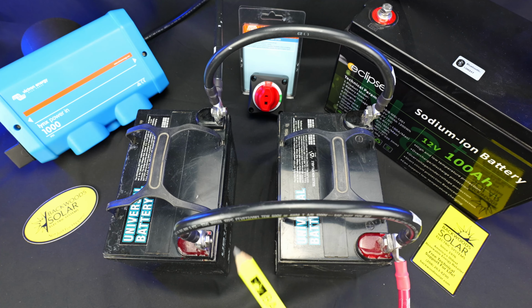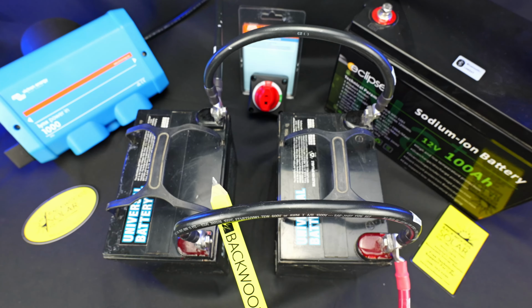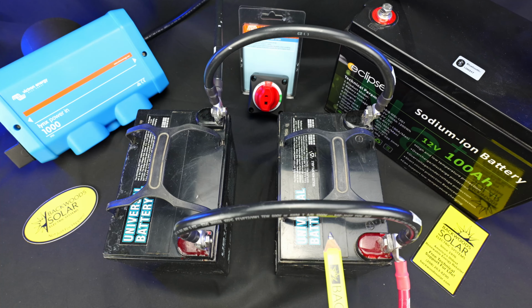In our example here with these two 12 volt 35 amp hour batteries, when wired in a parallel configuration like this, we maintain the 12 volt overall nominal voltage, but we add to the amps or the capacity of this bank. So now wired like this in parallel, we have a 12 volt bank at 70 amp hours. Again, each of these are 35 amp hours. So this gives us an overall bank of 70 amp hours at 12 volts.